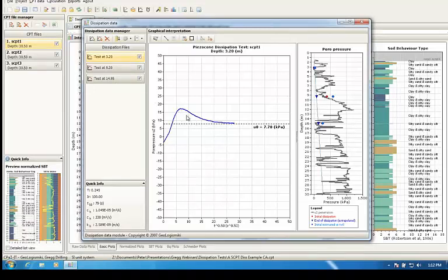And for low-risk projects, where often you just can't afford to do the lab testing, you don't have anything much better than this, but you do have to keep in mind that it's an accuracy to within about an order of magnitude. So although we're often calculating, as you see in this example, where it says 1.045 times 10 to the minus 5, I don't get too carried away with the decimal places in the calculation. It's essentially 10 to the minus 5 meters per second, plus or minus a half order of magnitude.